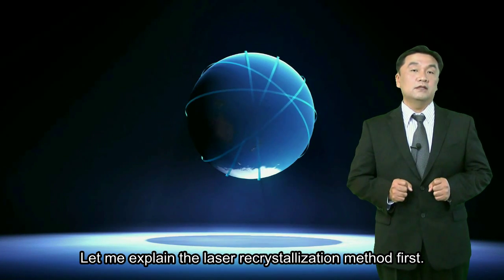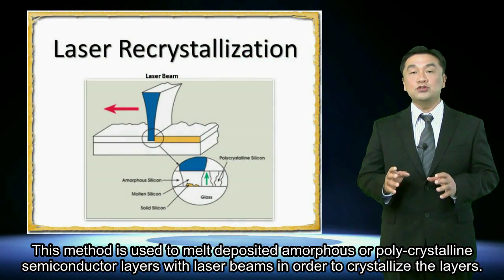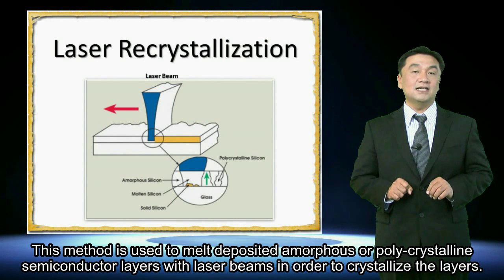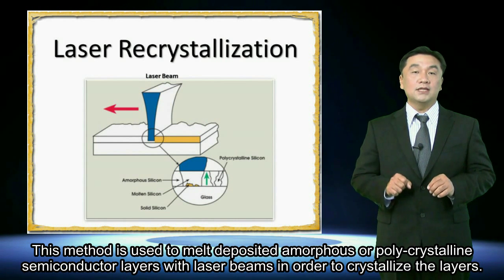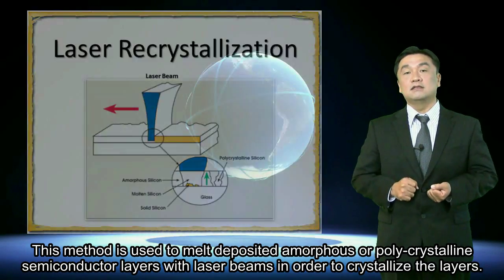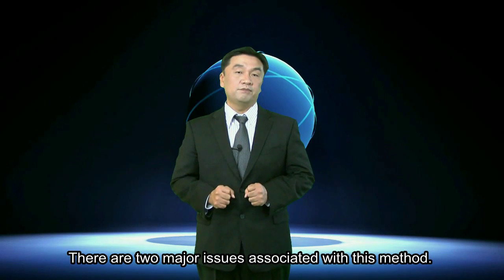Let me explain the laser recrystallization method first. This method is used to melt deposited amorphous or polycrystalline semiconductor layers with laser beams in order to crystallize the layers. There are two major issues associated with this method.